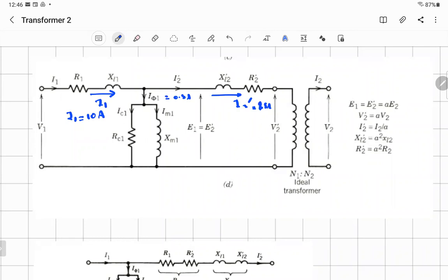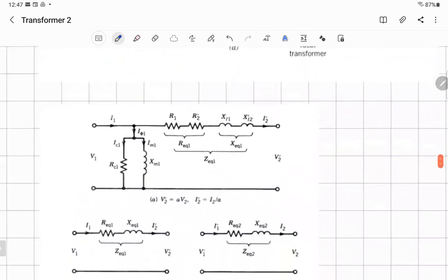So they found that, since that's the case, having a branch in the middle makes the circuit analysis complicated. And all the engineers try to find something simple that does not affect the final result. So we take the whole branch and move it here, so we can add R1 to R2, XL1 to XL2, which makes life easy. And that's what they did.